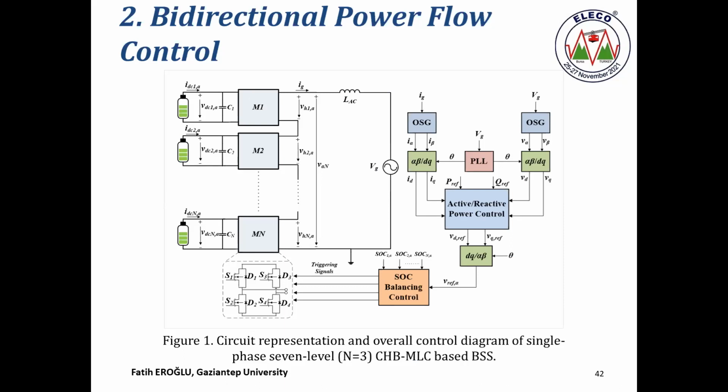Actually, there is no such scenario for fault conditions as you mentioned, but in terms of SOC balancing, there should be no problem again. We just need to isolate the faulty battery pack first, and then make sure the total voltage of the remaining battery packs is enough for the grid connection.